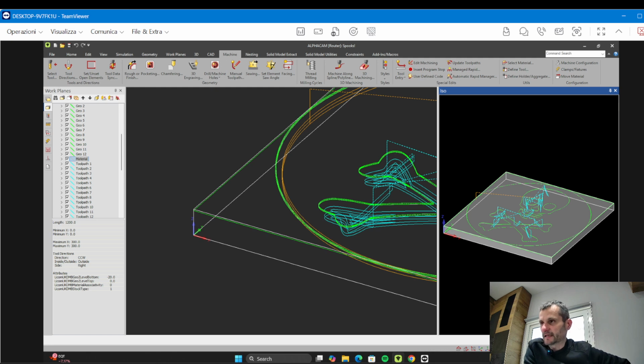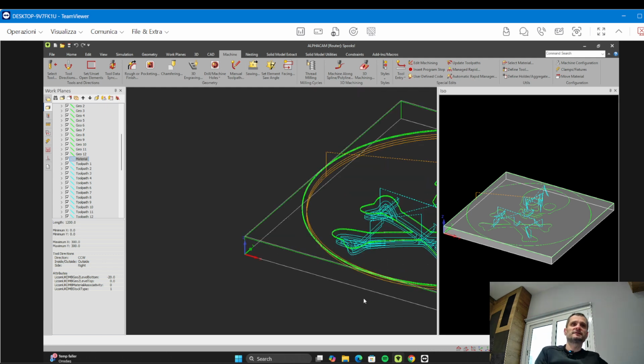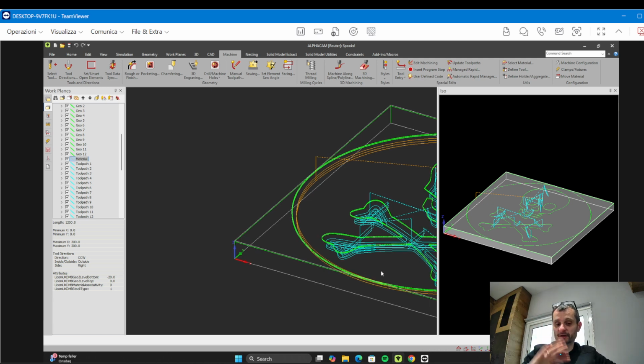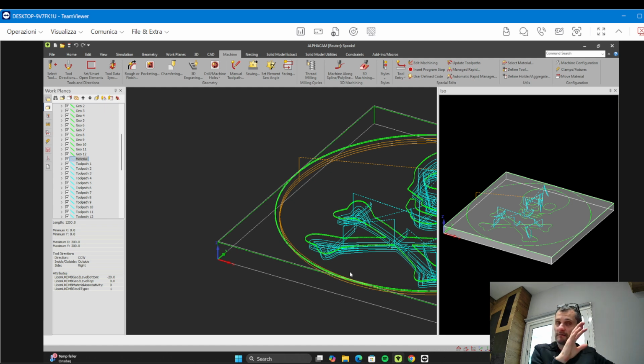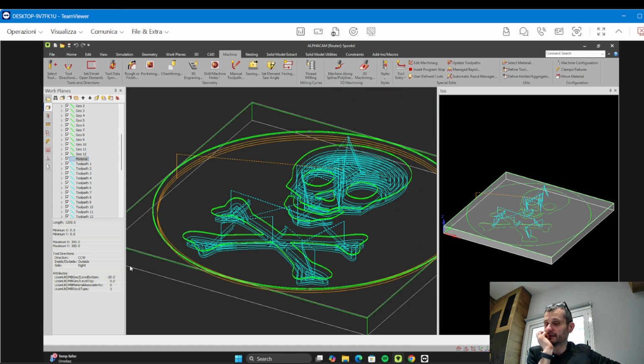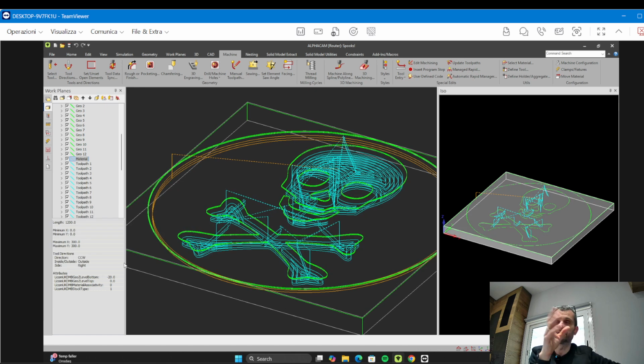You can try. What happened? Yeah. Nothing bad. I mean, you can break the tool. So if I have a 3 millimeter, I go down just one, for example. Okay. If you have to answer something, not more than one, because 3 millimeter is wrong, in my opinion. Start to think about, in my opinion, when you can choose nothing less than 5 millimeter diameter. Okay. So starting point is 5, 6, 7, and when it's bigger, it's better, of course.